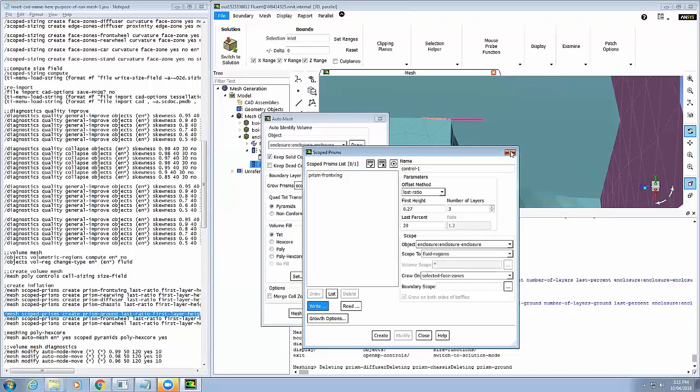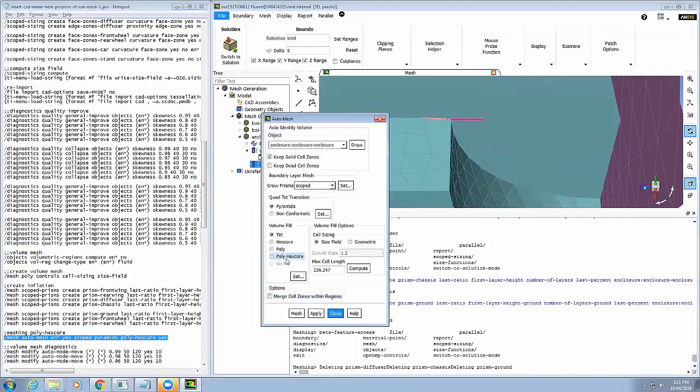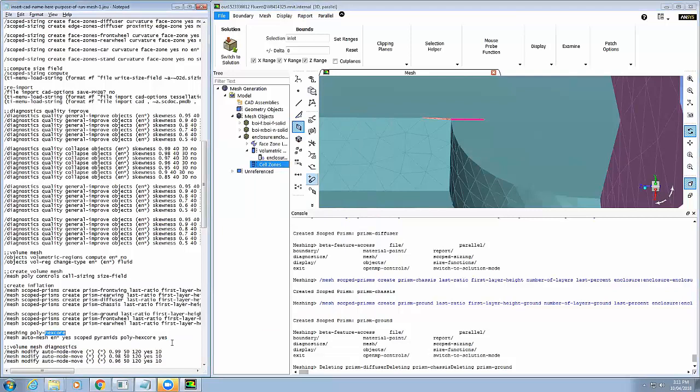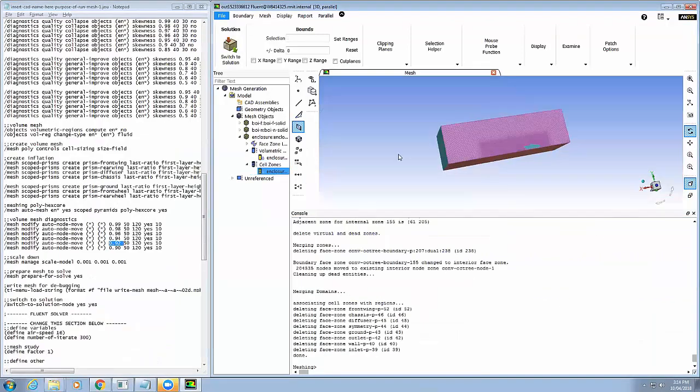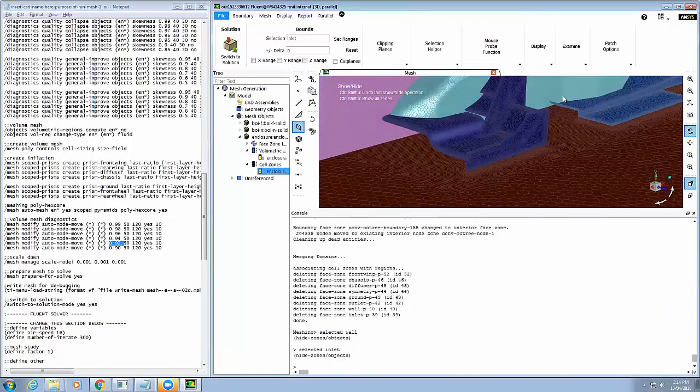Yep. Yep. Awesome. Close, close. Polyhex core. And so pretty much what you're doing in here, auto mesh, I'm going to polyhex core, and it's just going to run it, right? So instead, we're going to just use this function, and this takes a bit of time. Nice poly surface. Again, I'm just going to get rid of everything here. All right, everything's poly on the surface. Nice.